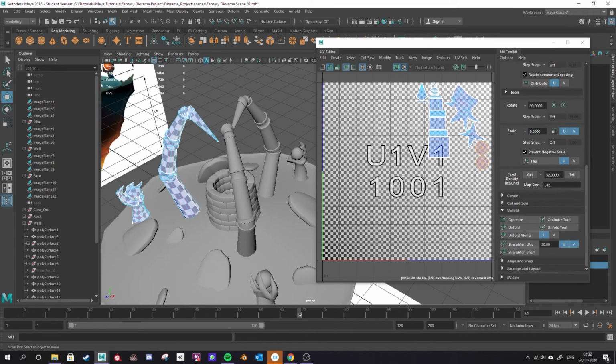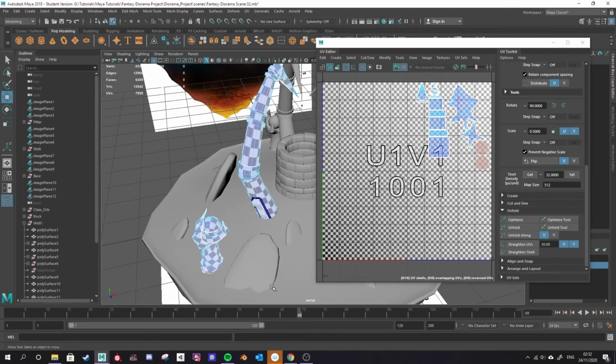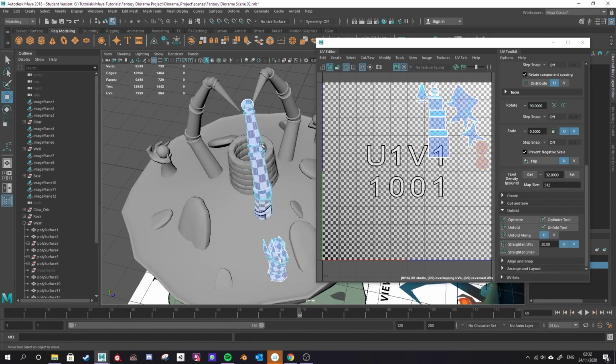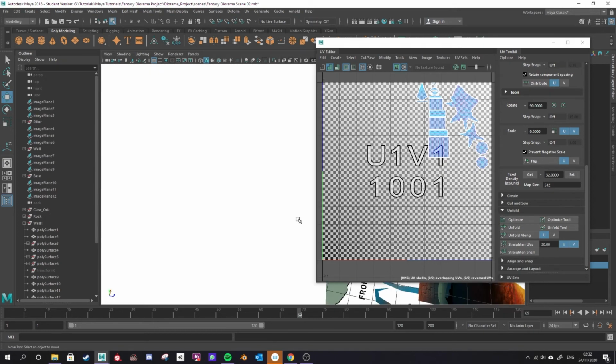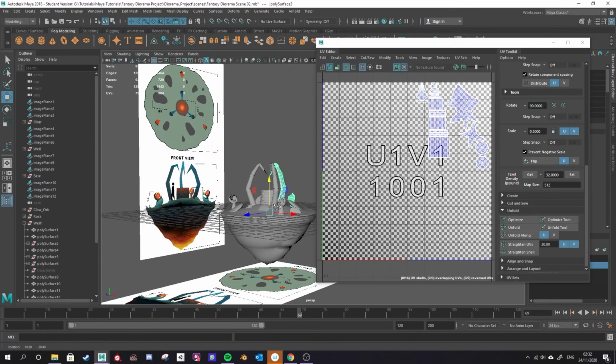So for instance, the stones here clip differently through the ground. If I used ambient occlusion maps on them, you would see the little marks where other stones are clipping through at different angles. So generally a bad idea to have all of this overlapping UVs, but since we're just painting an albedo texture for this hand painted look, this will work absolutely fine. So let's look at exporting this UV map then.